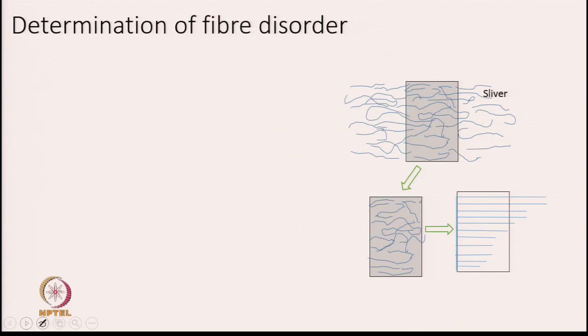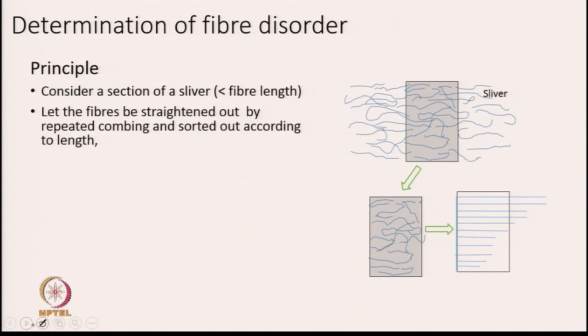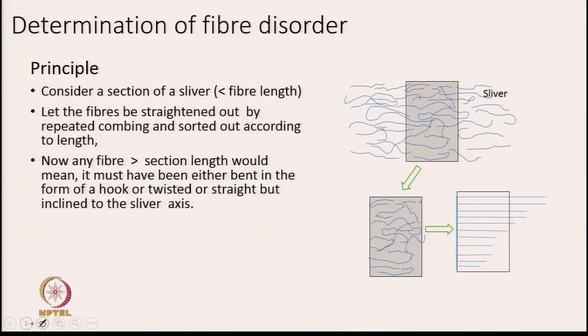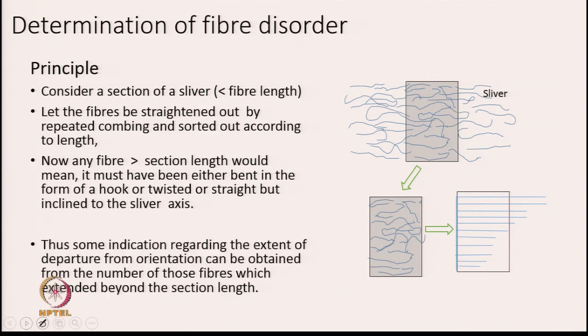This is the technique which has been shown by some people, so we try to understand this technique first. Let us take a sliver and consider a section whose length is less than the fiber length. So, this is the sliver, and let us take this section whose length is less than the fiber length.